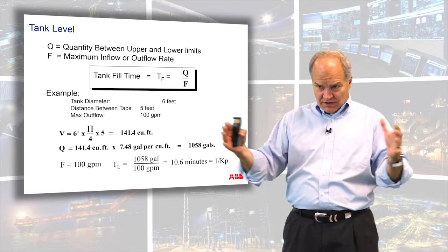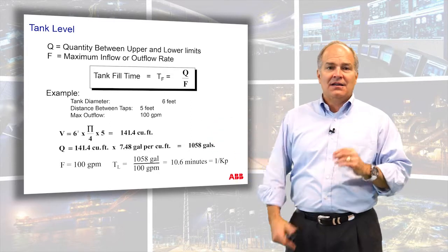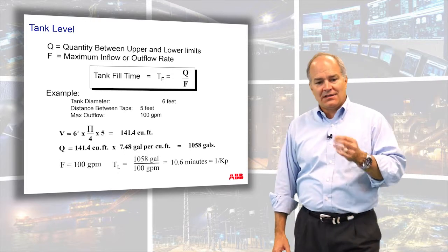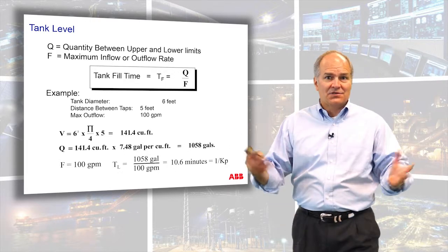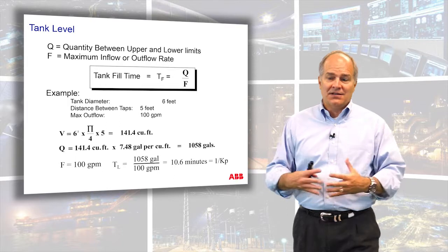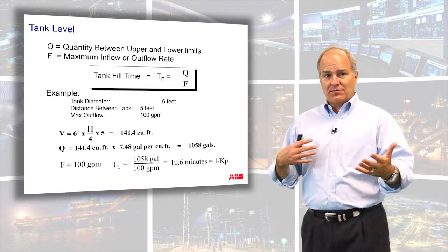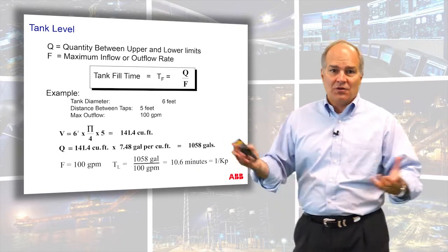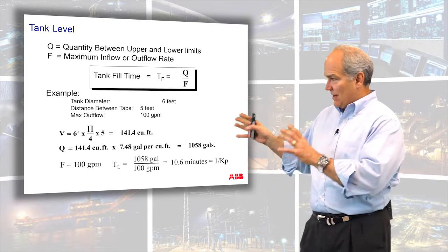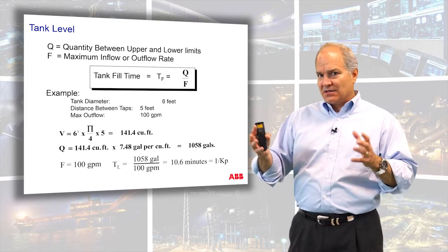So then I go and look at the tank size, and does that make sense? I always like to rationalize the numbers that I calculate with the physical size of the tank. It has to match. If it doesn't match or you don't feel comfortable with it, don't then use it in the control and hope it works. Go and make sure, does this look reasonable? Is this the right fill time?